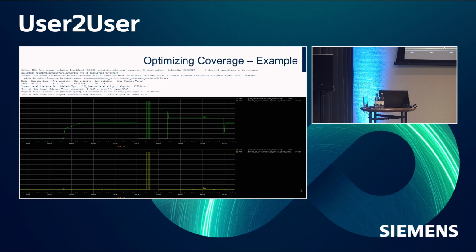You can see that this node is a primary output for the device, because we intended to spot the analog coverage when on the ATE. In this case, the primary output is stuck at 0. This allowed us to implement a test. Maybe in the final test on the ATE there is no test looking at this point, so this kind of failure would not have been highlighted.